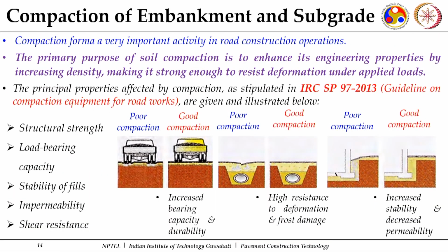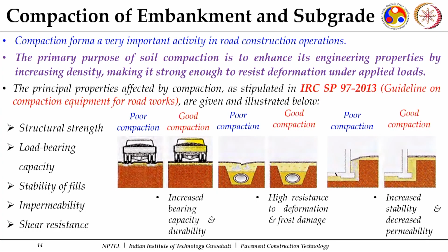Now, when we are going to place the layers, the existing land needs to be compacted. Whether it is the first layer of embankment or the first layer of your subgrade, the foundation over which it has to come up also needs to be compacted. So, why is compaction important? Compaction forms a very important activity in any of the road construction activities, whether it is construction of the embankment, subgrade, granular courses, or bituminous bound courses.